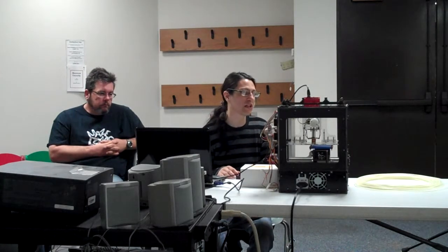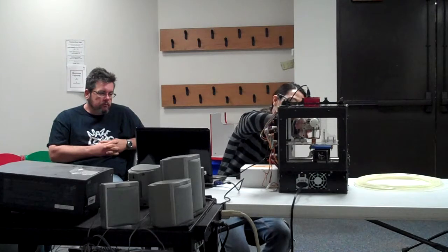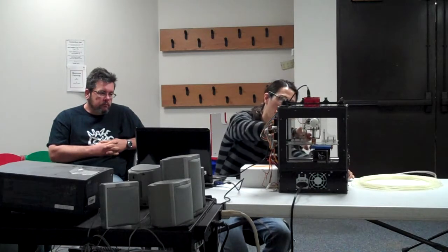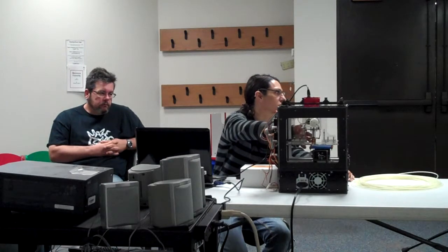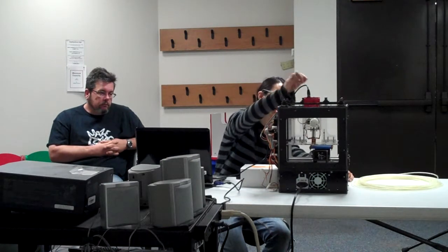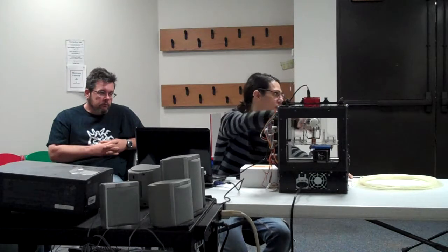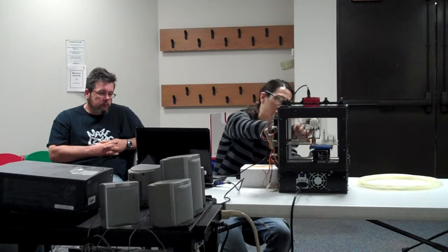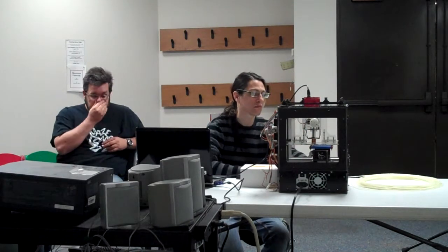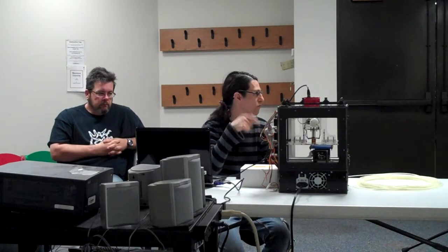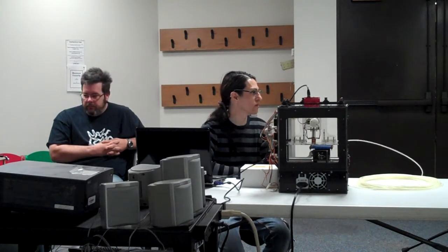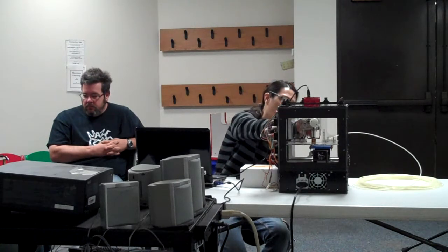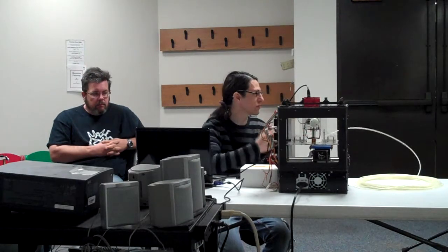I don't like to cool it down really quickly, because the plastic cools inside your element here and it'll get stuck. You don't want it getting stuck, because then it's hard to take out and you have to clean the inside of the mechanics here. So I usually keep it hot, pull it out, and then we refeed it. You could probably keep it in there and keep printing, but I've had problems doing that, because of the way it pulls the stuff down.